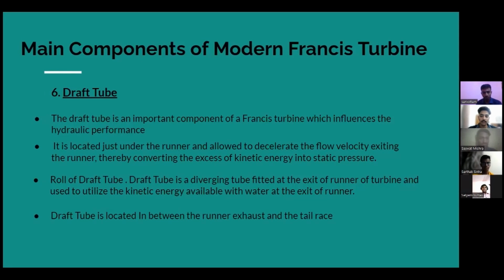Now, the last one is the draft tube. The draft tube is an important component of the Francis turbine which influences the hydraulic performance. The pressure at the exit of the runner of the reaction turbine is generally less than the atmospheric pressure.